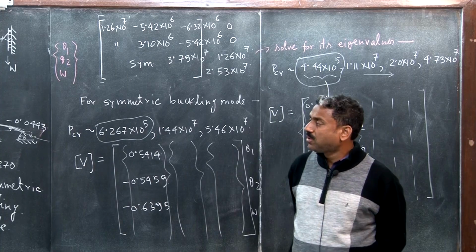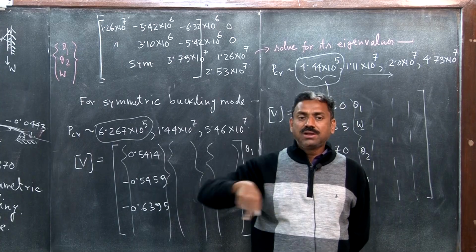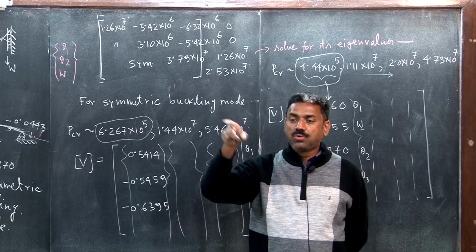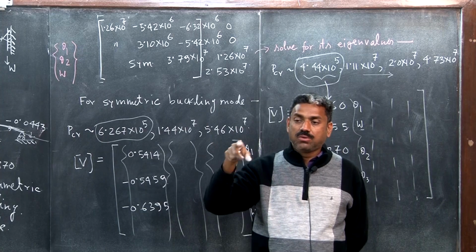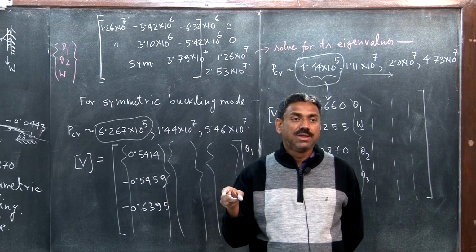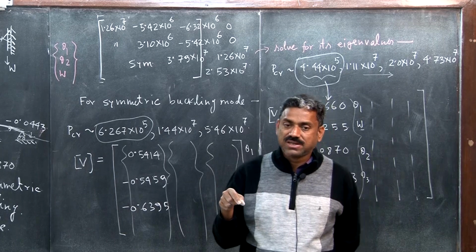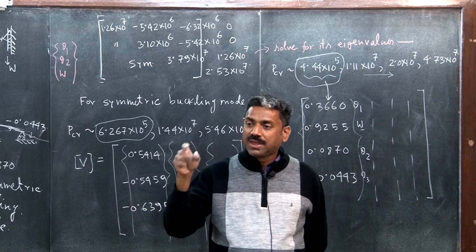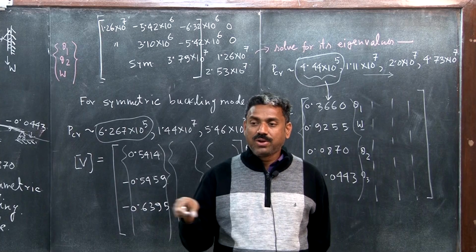So, there needs to be one loop over element, one loop over the element nodes, another loop over the degrees of freedom. Then, because you have i and j, two indices for the stiffness matrix, you will have another nested loop over node and degrees of freedom.